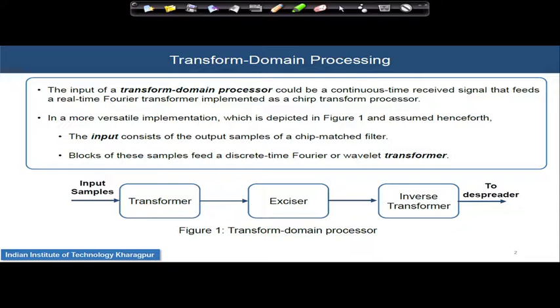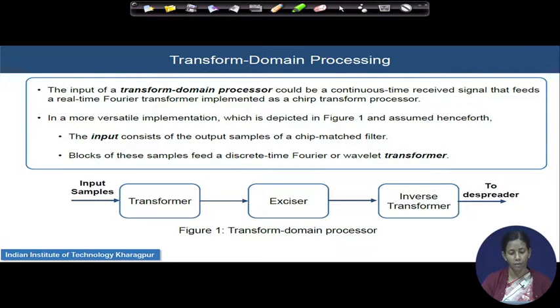The transformation algorithm is designed in such a way that in the transform domain you can easily distinguish between the interference and the desired signal. If I see the output of the transform over the different transform domain beams, you will see that the interference resides in a small beam, compared to the uniform amplitude of the desired signal that is spread over all the beams.